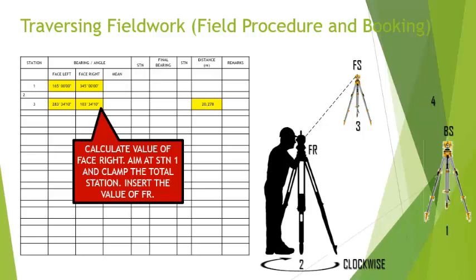This is the end of the acquisition process on the current station, or station number 2. Finish. Leave the tripod with prism on station 1 and move it to station 2, while the total station at station 2 is moved to station number 3, and the tripod with prism is set up on station number 4. This is how you move to the next.